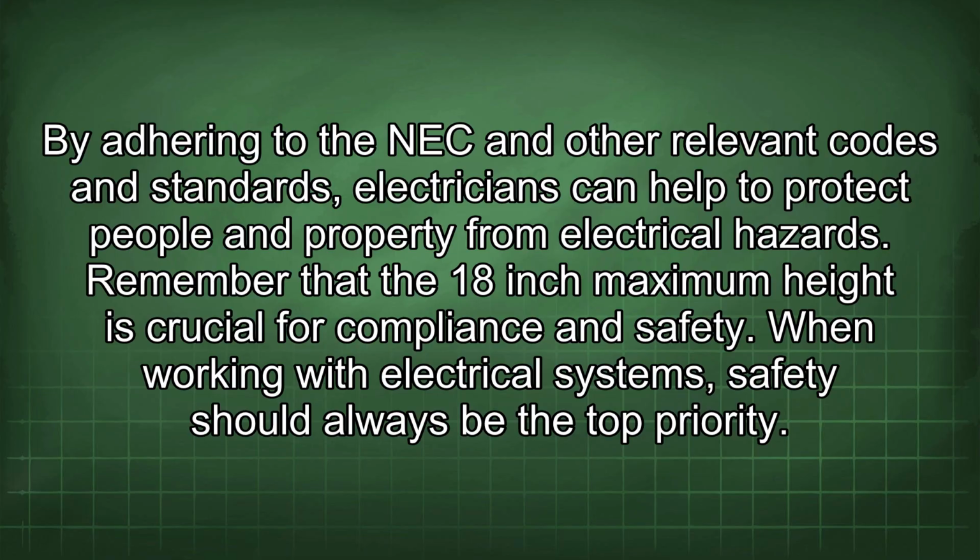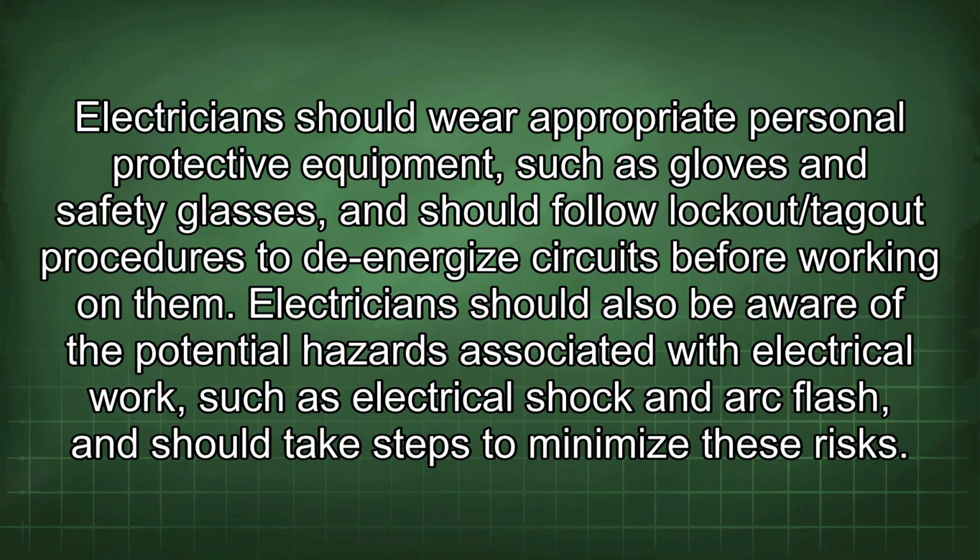When working with electrical systems, safety should always be the top priority. Electricians should wear appropriate personal protective equipment, such as gloves and safety glasses, and should follow lockout/tagout procedures to de-energize circuits before working on them. Electricians should also be aware of the potential hazards associated with electrical work, such as electrical shock and arc flash, and should take steps to minimize these risks.